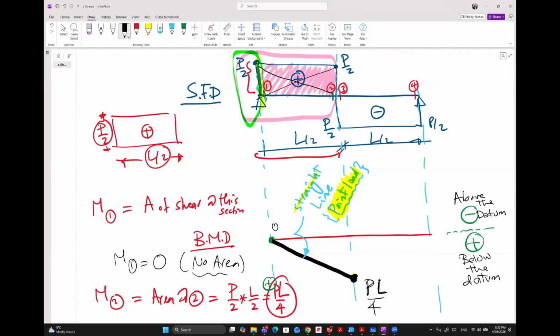Say it, Matthias. Sorry, I disturbed you. What did you want to say? I say it is the same: P over 2 times L over 2 is the same. So same area, so same moment, right? So the moment at 2 and 3 are the same. Now, what is the moment at 4, guys? What do you expect? The moment here is 0 as well. So the moment is 0 at these two points, and we connect from here to here with another straight line.